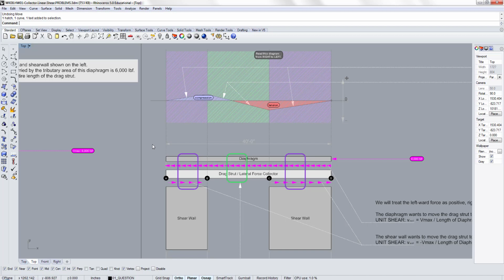So in this case, point B experiences maximum compression, and point C experiences maximum tension. So you have to design this beam to be able to resist the tension of that amount and compression of that amount.